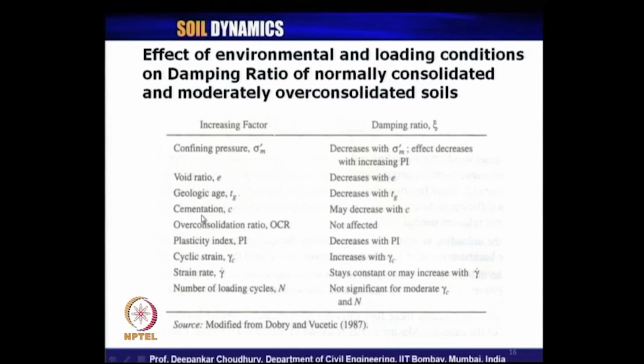What is the effect of cementation? With increase in cementation in the soil, the damping ratio may decrease, but it is not so significant. So, the effect of cementation on the damping ratio is not very significant. The trend is a minor decrease in the value of the damping ratio with increase in cementation.